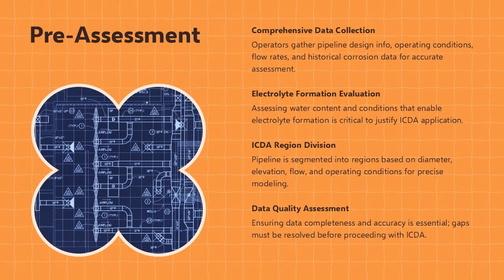Pre-assessment is the foundation of the ICDA methodology and determines whether ICDA can be reliably applied to a given pipeline segment. During this step, operators collect and review all relevant data, including pipeline design information, alignment sheets, elevation profiles, operating pressures and temperatures, flow rates, product composition, and historical corrosion or failure data.